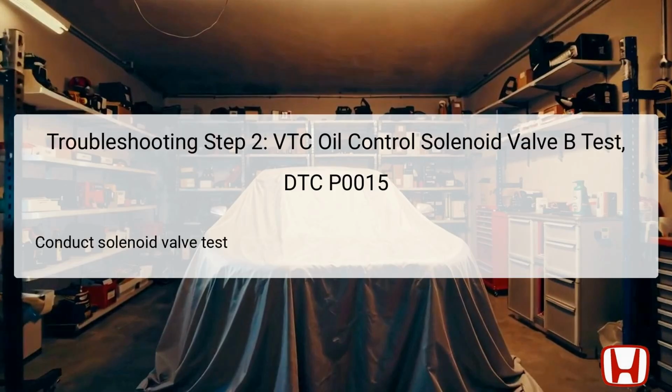The next step in resolving the DTC P0015 is to perform a test on the VTC Oil Control Solenoid Valve B. This component plays a vital role in regulating the oil flow to the VTC Actuator B, directly impacting the camshaft timing. To conduct this test, first, ensure that you have access to the vehicle's diagnostic tools.